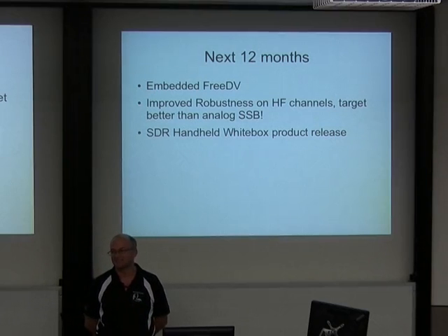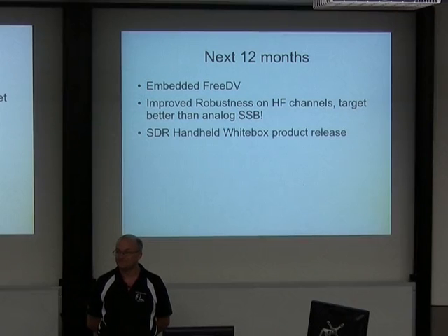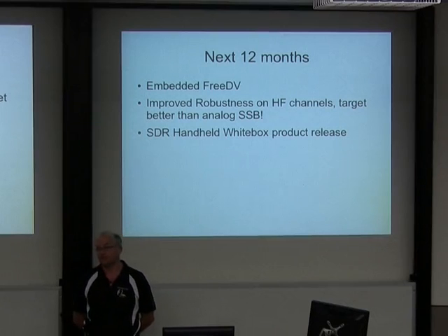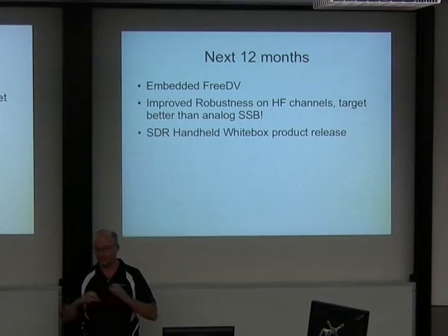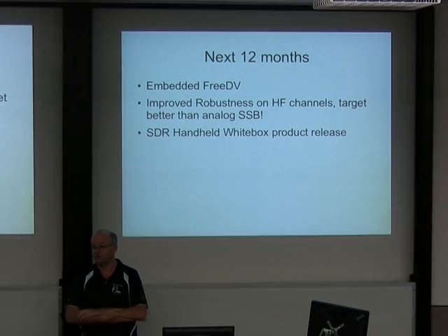Has there been any work on moving Codec 2 onto some of the... Yeah, there is a lot of talk about a VHF mode, and some protocols have been designed, even some modem code available. No one's really put it all together. What would be possible as a first step is simply to bundle some of this code up in FreeDV with another mode, and using the Sound Blaster interface, plug it into a VHF radio. So that's something we're waiting on. Someone's really just got to do it, that's all.